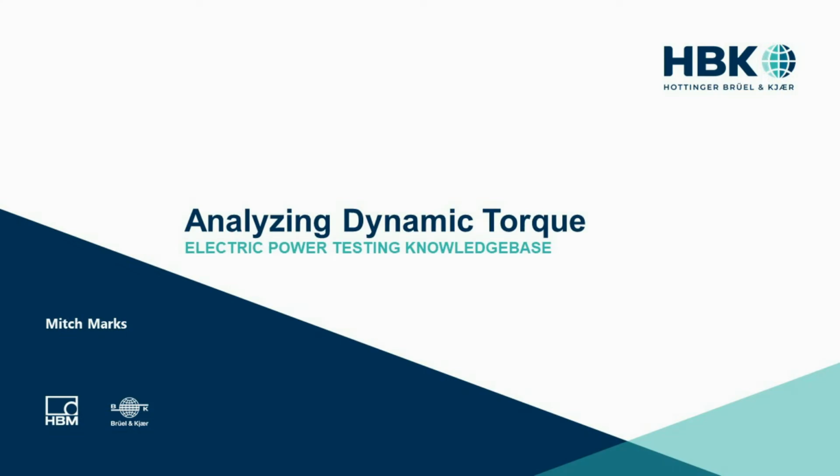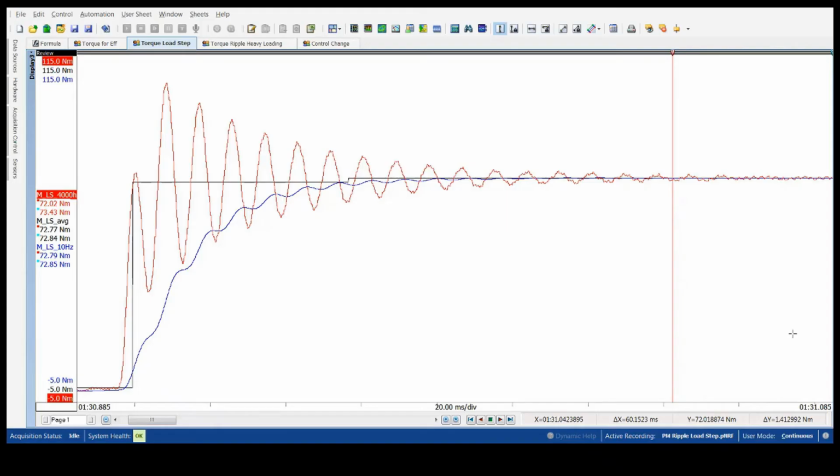The second test we will look at is a highly dynamic situation of a motor at 5,000 RPM and zero torque initially with a 70 Newton meter load step. The electrical characteristics respond very quickly, and what I have displayed on the screen is just the torque. In the red we have full bandwidth torque, in the blue we have a 10 Hz filter torque, and finally in the black is the cycle average torque that is calculated the same way as the previous section.